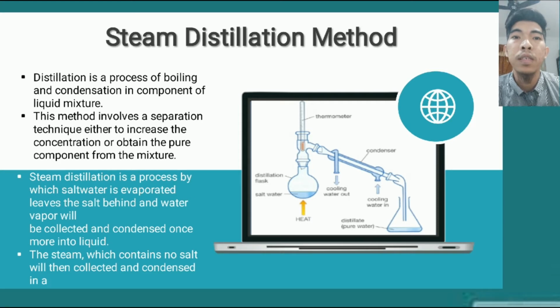Okay. Steam distillation is a separation method used to purify temperature-sensitive substances such as aromatic compounds. The goal of this process is to introduce heat and separate the components at a temperature below their decomposition point. Steam distillation is a method used for distilling highly sensitive compounds. The temperature of steam distillation is much easier to control than the temperature of a surface heating element. Then it allows a high rate of heat transfer without the need to heat to a very high temperature.